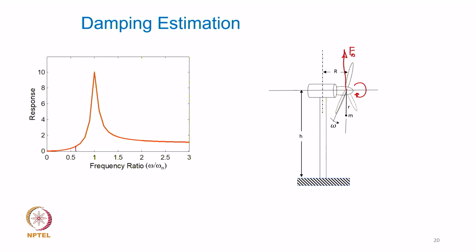Now, if I start rotating this shaft at different speeds, I know that as the speed increases the amplitude will keep on growing. As it nears the resonance, or undamped natural frequency of the system, it will peak, then fall and go flat from there, right. So, suppose I practically measure the vibratory amplitude. I can always show an equivalent vibratory system as a simple spring mass system, and this excitation force acts on the mass and creates a forced vibration response.